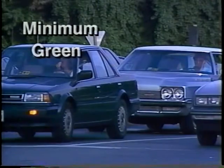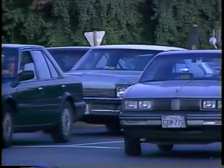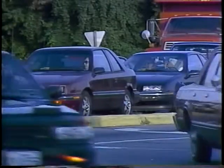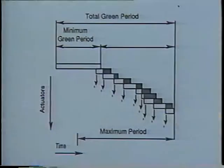The minimum green interval is the amount of time a detector allows for a stopped vehicle to accelerate and move into the intersection. When a type of point detector, such as a 6x6 foot loop detector, is used, the minimum green interval allows a vehicle stopped between the detection point and the stop line to comfortably move into the intersection. Presence detectors with loops ending at the stop line require a different timing approach. In this situation, the minimum green interval can range from 0 seconds for a turn lane requiring a quick response to a longer period of time for straight-through vehicle movements.